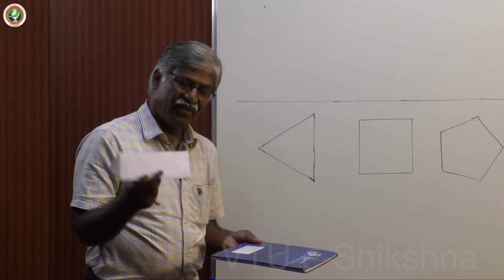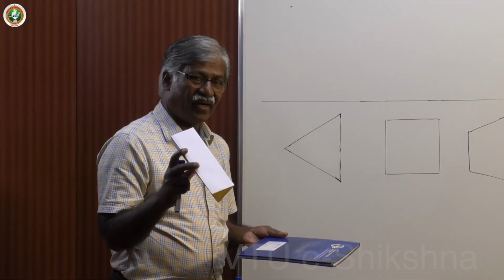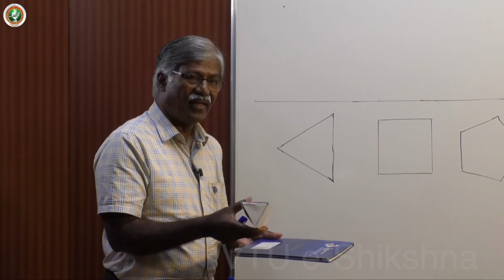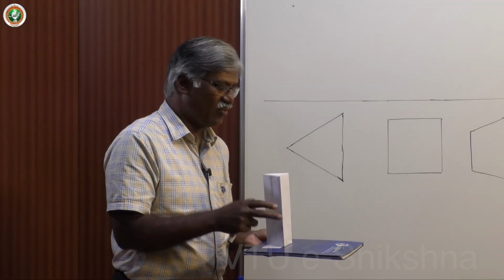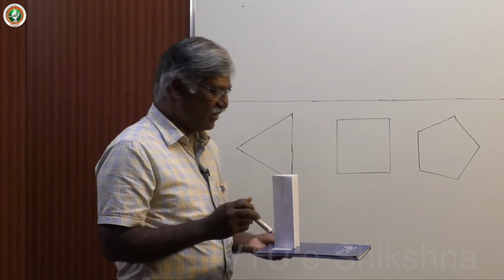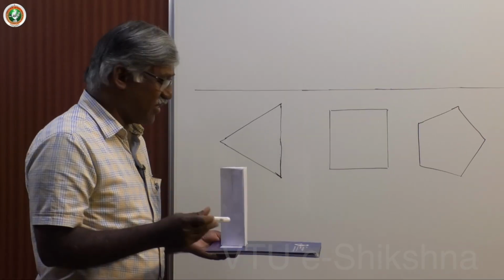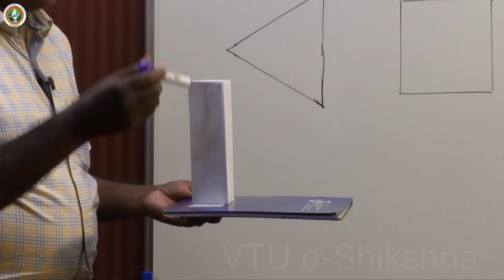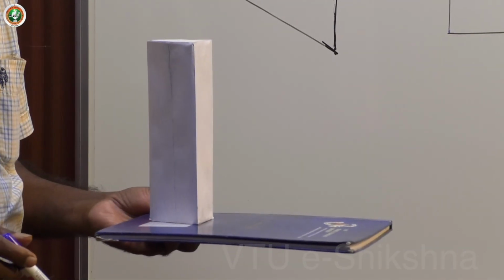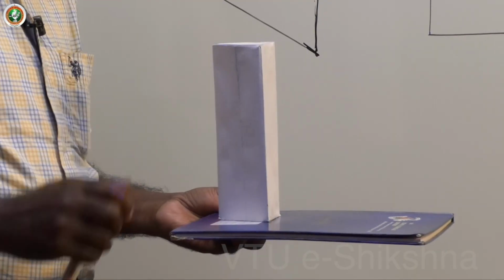Always, in future, I will refer to the dark side as the base, and the surface is also referred to as base. Okay, for our reference, the light color refers to the top face, and naturally the surrounding lateral surface will be white only, surrounded by the blue color longer edges. Now this particular position is referred to as a rectangular face perpendicular to VP, or one of the base edges is perpendicular to VP.